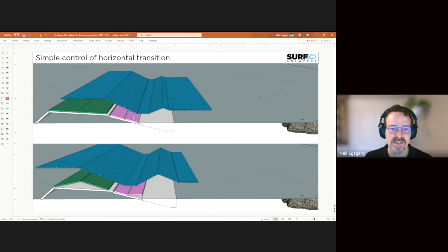And then the last piece is this kicker here. These two kickers here, all they are is hinged. They have a very slight movement. They go from a down angle to horizontal. So in the lowest flow conditions, we have everything down. The wave comes over the drop and it forms based off of the tailwater elevation above this pad.